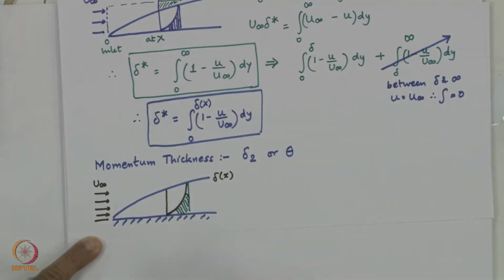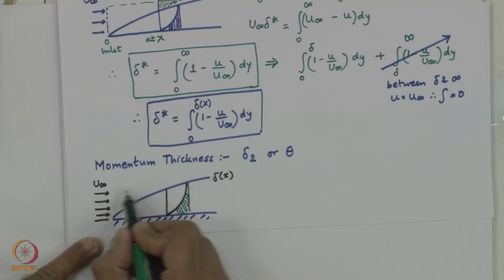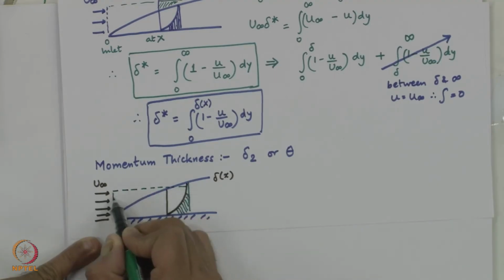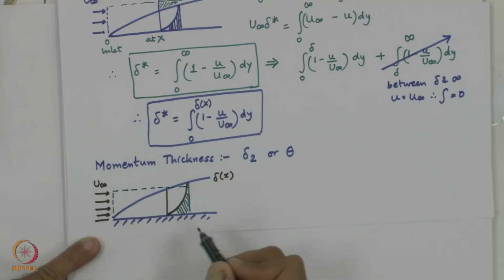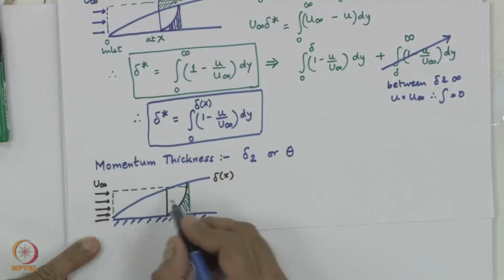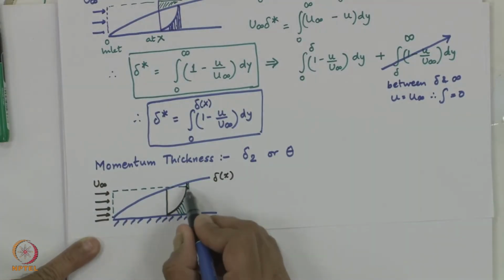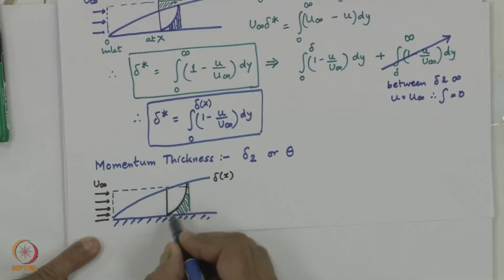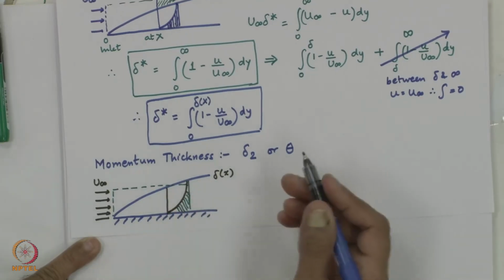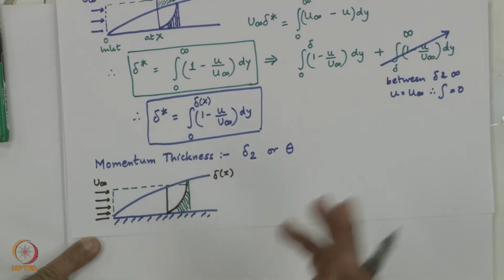velocity profile. So, the momentum that the fluid is carrying out, if I look at a control volume, which let us say is given by this one, the green one is my control volume, right. So, this control volume has a velocity at exit. Remember, the velocity profile would always be such that it is 0 at the wall and 0.99 times u infinity at the edge of the boundary layer, that is the definition.